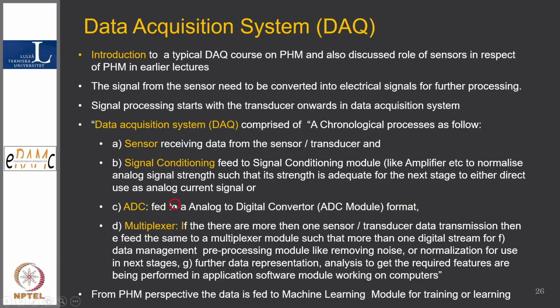Now if you see at the level of a plant, there will be many components that you would like to monitor. So the signal will not be one; there will be many digital signals that you are getting from the plant. Every signal has to go through the ADC and become a digital signal. So how to do that? The multiplexer is a critical component for that.